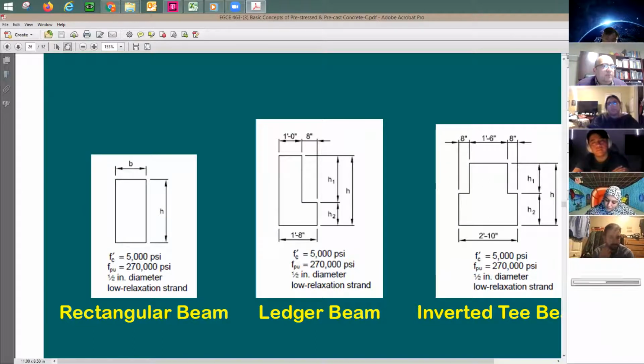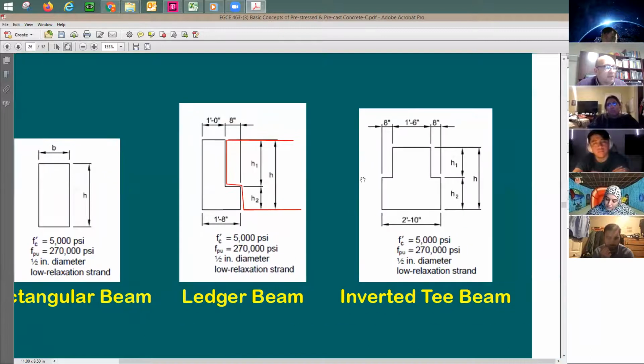So in some cases, we put the double T like this. The double T is going to come like this, and the notch is going to be like this, so it comes and just sits in it. So sometimes you have a ledger beam and it's going to be only from one side. Sometimes you have it from both sides. So this is good here as a central support if you have double T's, one on each side. And this one here, if you just have it from one side, the other side is going to be open. And in a case like this, as you see here, we don't have a parapet, which means a spandrel, right? So in some cases it comes without it.